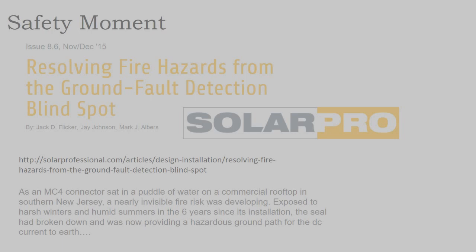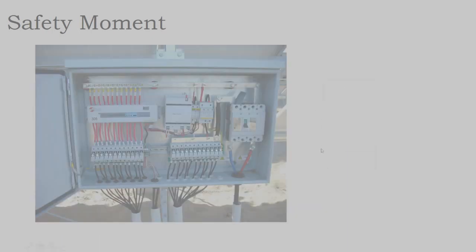Does it reference a voltage to ground, or does it monitor that voltage in a different manner? Is it a grounded or an ungrounded inverter? And in grounded inverters, when you have multiple strings, there's a blind spot in the old school central grounded inverters on commercial systems that has burned a couple buildings to the ground. I guess that's a bad pun.